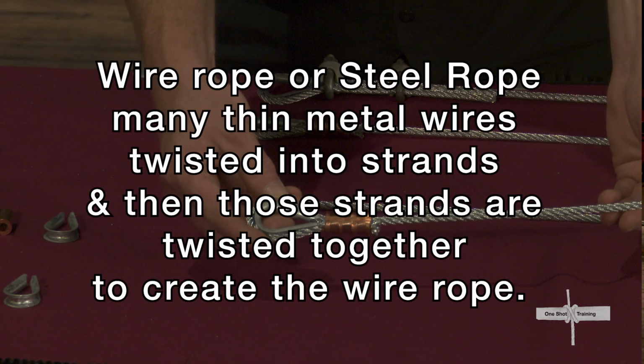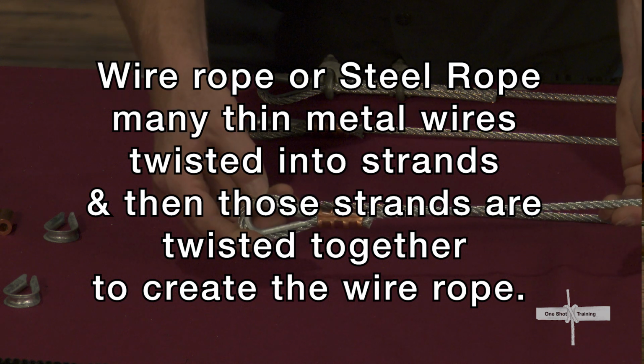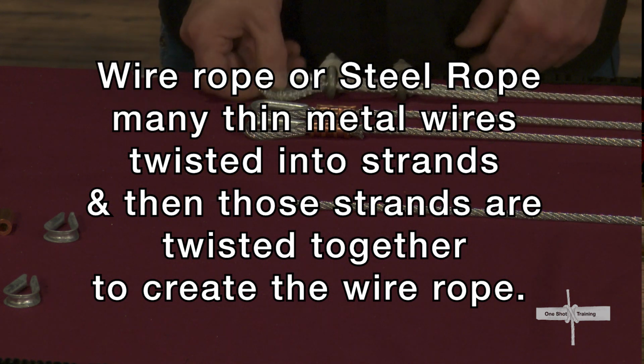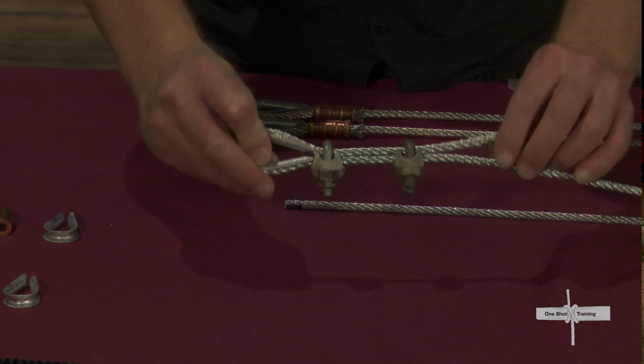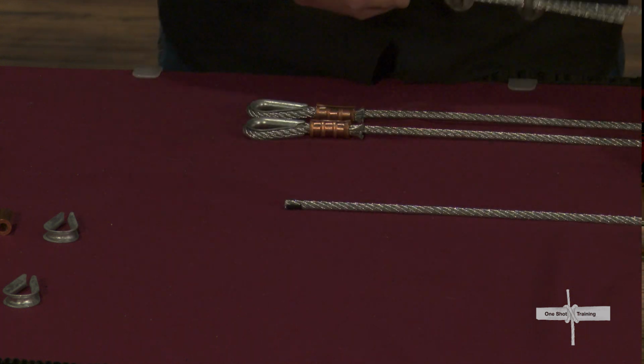Wire rope or steel rope is made of many thin metal wires twisted into strands, and then those strands are twisted together to create the wire rope. It typically has a swage eye built into the end, which you can use with shackles to attach other things to that cable. It's possible to tie a knot into smaller diameter versions of wire rope, but that rarely happens in workplaces.